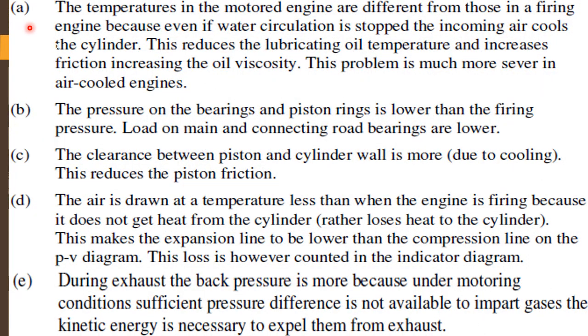So what you can see here, for different reasons, the temperatures in the motored engine are different from those when firing is observed, because even if water circulation is stopped, the incoming air cools the cylinder. When there is no firing, the fresh charge is entering the system and the cylinder temperature is decreasing. This reduction in temperature reduces the oil temperature and increases the friction, plus increases the oil viscosity. This problem is much more severe in an air-cooled engine. So when we cut the fuel supply, this is observed.